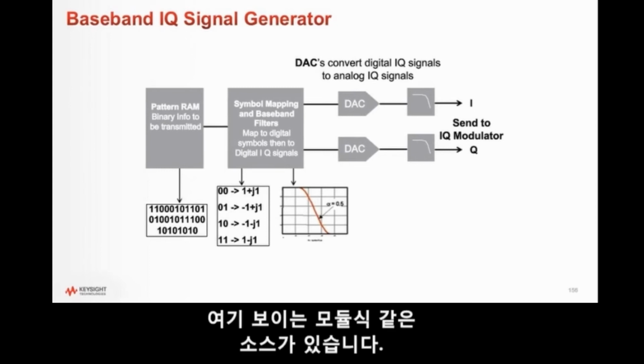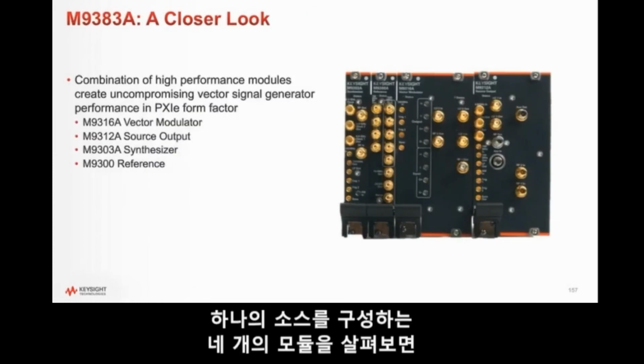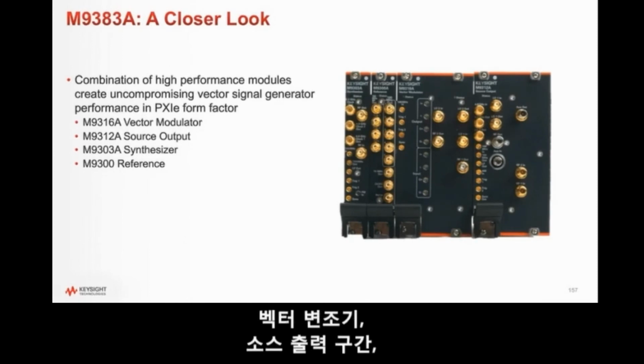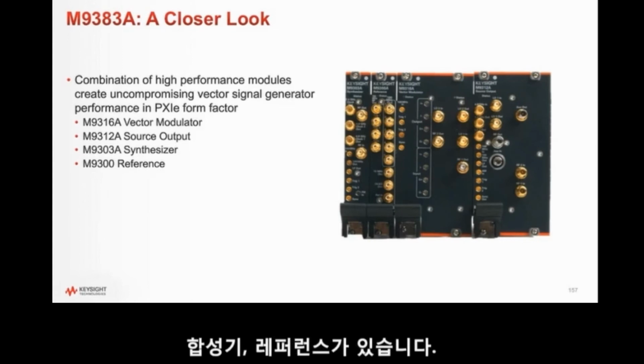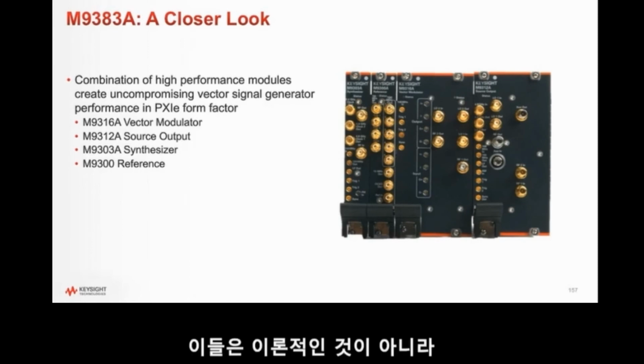We have sources like this one here that are modular. If we look at these four modules that comprise one source, we have a vector modulator, we have a source output section, we have a synthesizer and a reference. These are all the blocks that we've been looking at. So this isn't a theoretical thing. These are real chunks.